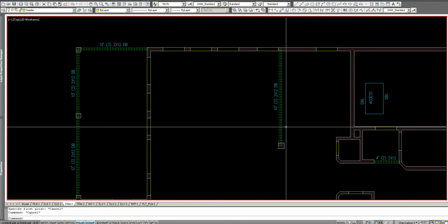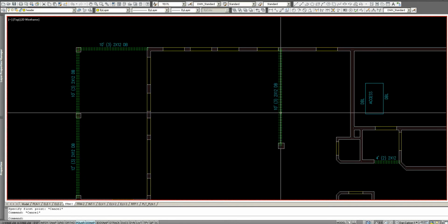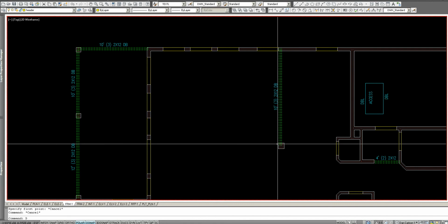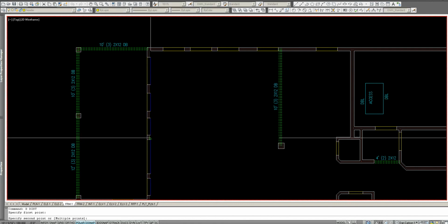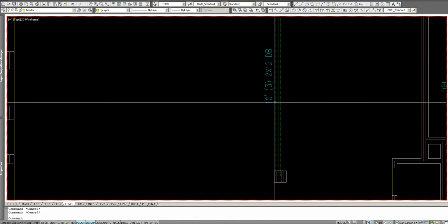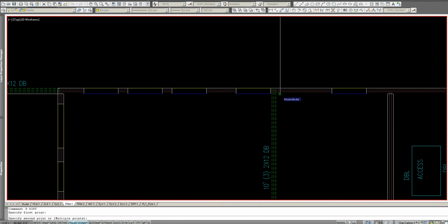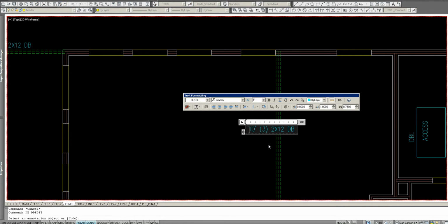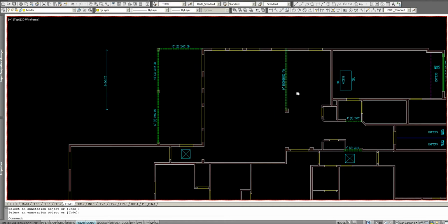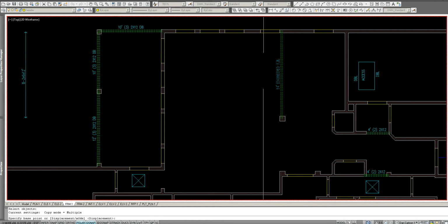So what we will probably want to do for that, since we don't know for sure how much deflection this beam can handle, is just call this a 14-foot engineered flush beam. We want it to be up in the ceiling, not dropped down.